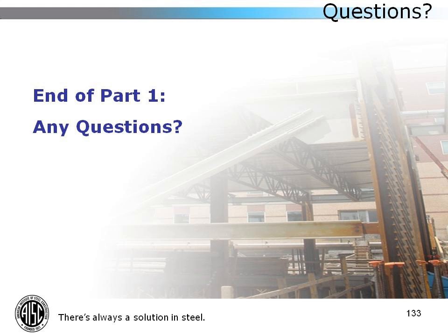What I'm saying is that you should use at least a number of studs to get you, I recommended 50%, absolute minimum 25% of composite action. So you're certainly welcome to design them as if they aren't there, but at least put enough studs on there to achieve 25 to 50% composite action to allow some reserve capacity and ductility within these stud anchors. Don't just put a few studs on there. So if the minimum number of studs based on your maximum spacing is not getting you to that point, then no, that's not correct. You need to put more than that.